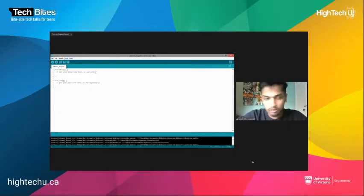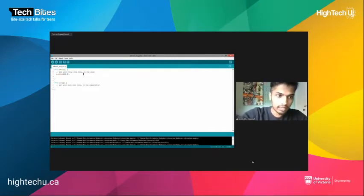Now, as it says here in void setup, you put your setup code here. Whatever pins you are going to use in the Arduino, let's say for now we are going to use a digital pin, you tell the Arduino that you are going to use that pin as an output port or as an input port. The LED comes as a load, so it is an output port. So you write pinMode, the pin number that you are going to use. In this case, it is pin number 13, and you're going to use it as an output port.